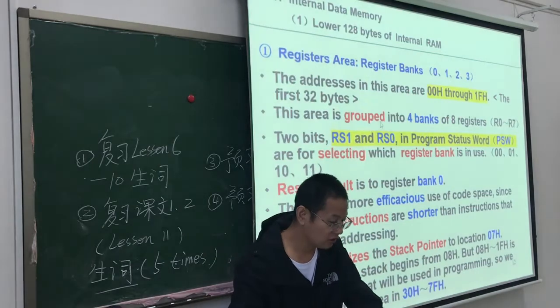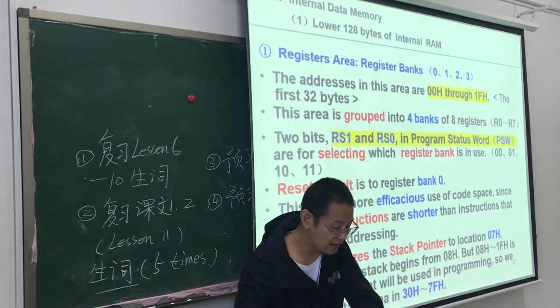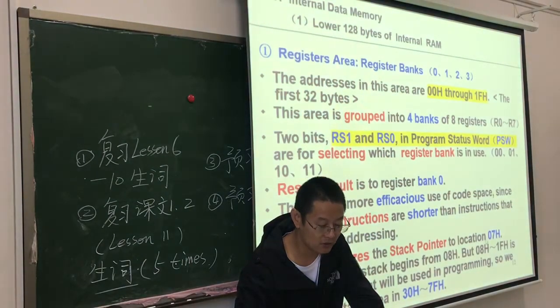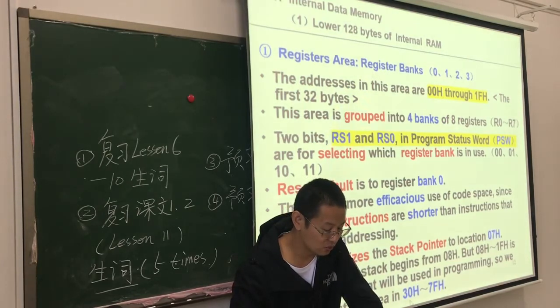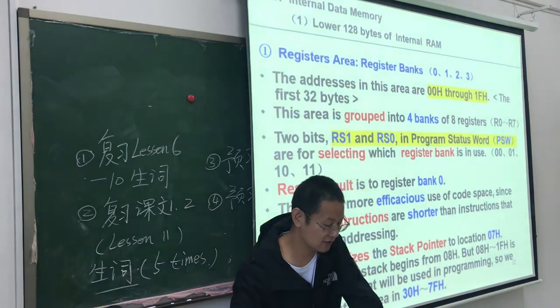Something special: reset initializes the stack pointer to location 07H, but we do not commonly use it. We will change the location to 30H, which is special.